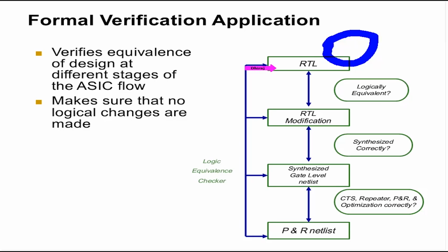You can work on the RTL, and now you can use a formal verification tool like Formality to make sure that the modified RTL matches the RTL that passed your stimulus, right? Now let's say the RTL is of a medium size design. The process of checking whether they are logically equivalent through Formality or NEC will take about an hour or so. For an even smaller design, it will be still quicker. For a decent size design, it might take even an hour, or a few hours, not more than that.